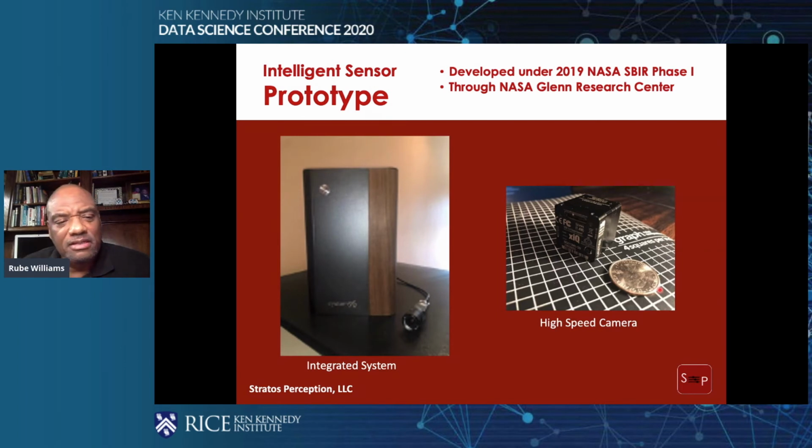In an actual implementation, and this is a prototype, this computer would be quite small. This is something we had on hand that's useful for us, and I think it runs a single NVIDIA 2070 GPU. We do the development in the cloud, so this one couldn't support exactly 1,000 frames per second, but straight away maybe about 300 frames per second, and we could do some fancy work with the circular buffer on the camera to get what we wanted.